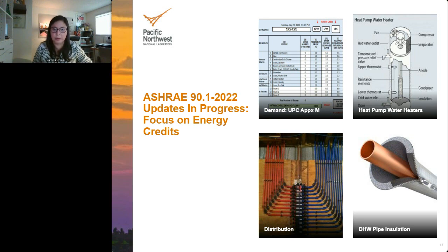We're incorporating heat pump water heaters and the efficiencies that we can gain from this new category, both on the unitary side, meaning the smaller household style heat pump water heaters, as well as the larger distribution systems for central systems. We're also looking at distribution, meaning can we incentivize shorter pipe runs, reduced recirculation losses, et cetera. And then domestic hot water pipe insulation.